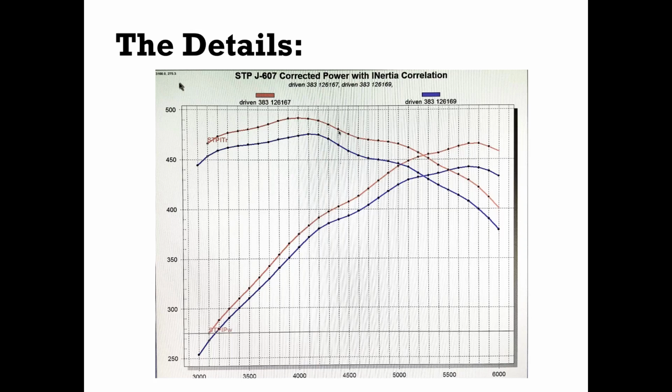So you have to watch the oil level and not just keep putting in oil, because what will happen is if you put in 6 quarts of oil and you drain out 6, and then you put another 6 in, you're not going to have 6 quarts of oil in the engine. You're probably going to have 6.25. If you do that over and over and over again, pretty soon you're going to be at 6.5, maybe even 7 quarts of oil, and now your numbers are going to be skewed because of not having the proper oil level.